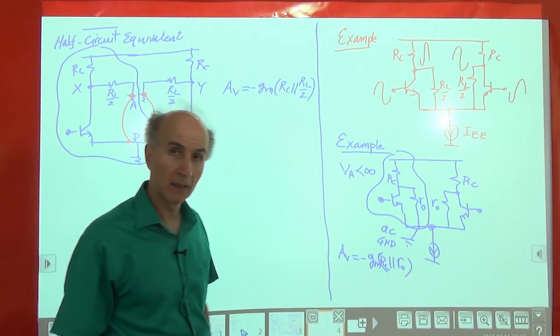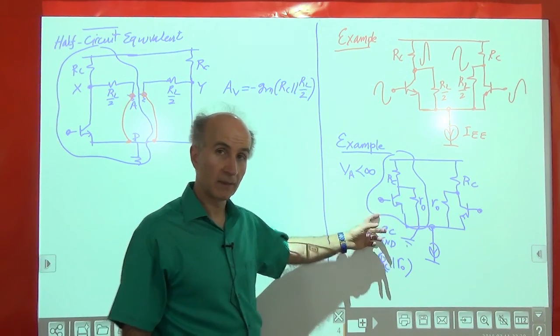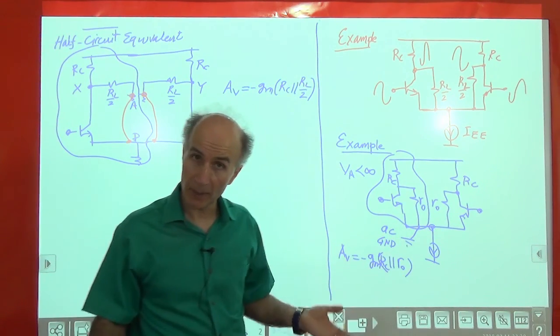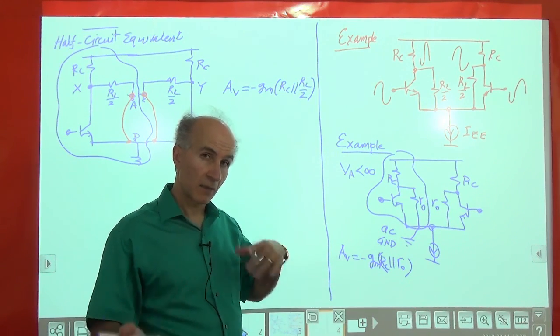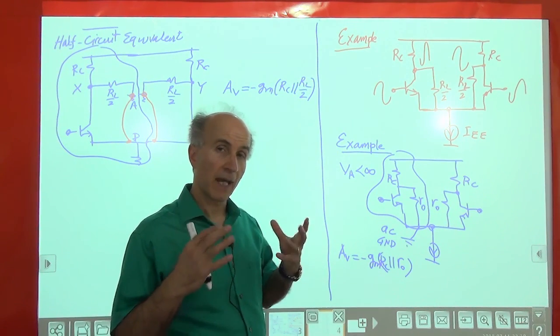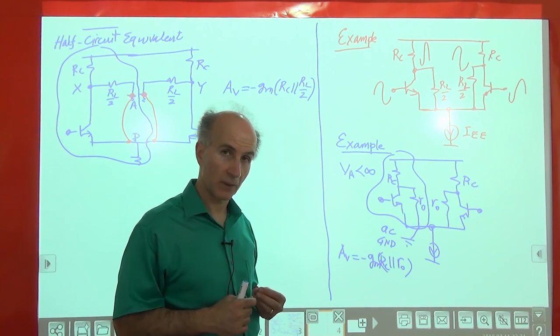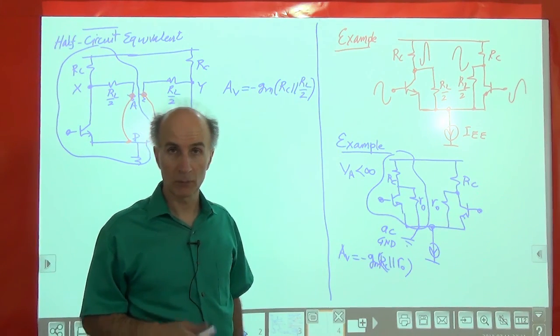And we saw that a small signal gain could be obtained if we recognize that this point is AC ground. That should also be applicable to MOS differential pairs because we didn't really assume anything about the actual characteristics of the transistors in that calculation, and so forth. So there are many interesting things that will come out when we get there.